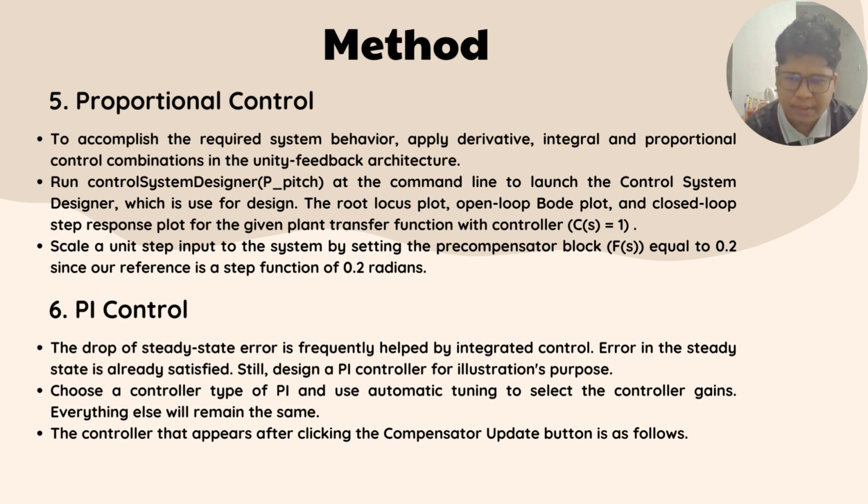And scale a unit step input to the system by setting the prefilter block F(s) equal to 0.2, since our reference is a step function of 0.2 radians. Next is PI control.